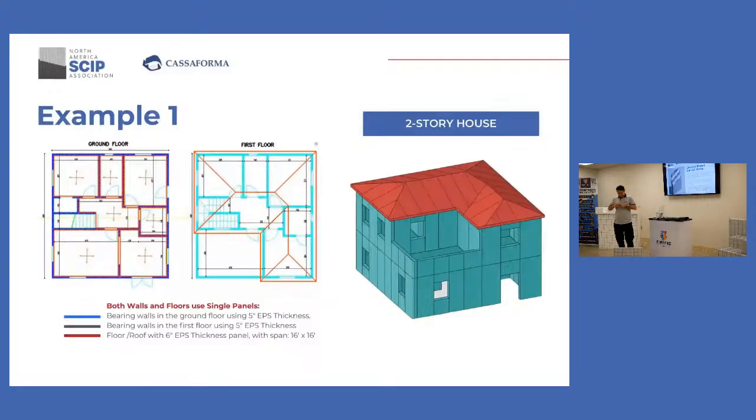Oh no, I was placing it the other way around. Now it is. So what I was saying is that you can tell while you are erecting. You never place a panel alone. You always begin by a corner, because that is how it works. It works by shape, because that provides you inertia. So you have to work with shapes. You have to create U's. You have to create L's.